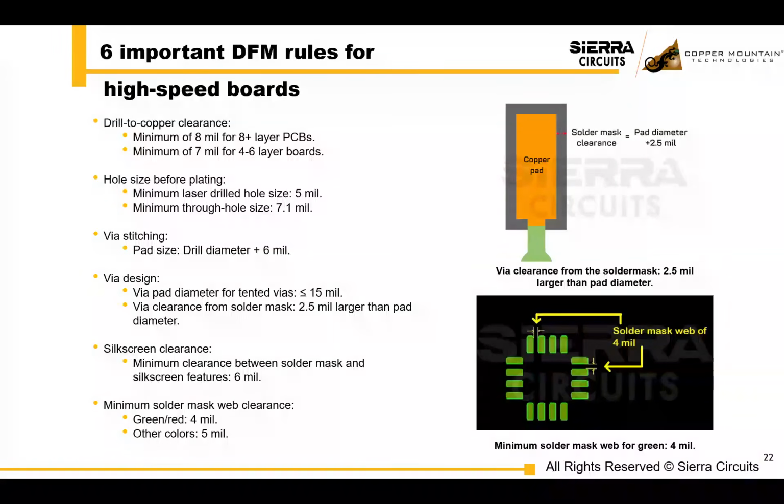I do want to point out solder mask. A lot of people just give a solder mask 1-to-1, and if it's a standard board, that's fine. But if there's any learnings that you have from after assembling the board, you want to modify your solder mask and even modify your paste layer for any sensitive components or components that you're learning from after the assembly. So the whole process should feed back to your pad design, your solder mask design, and your stencil design.